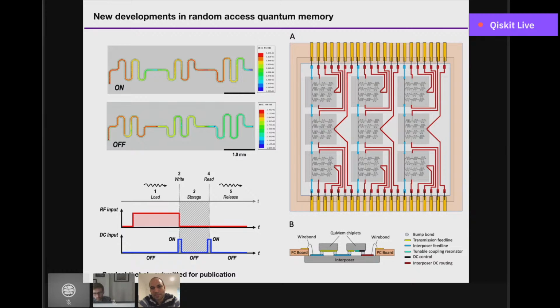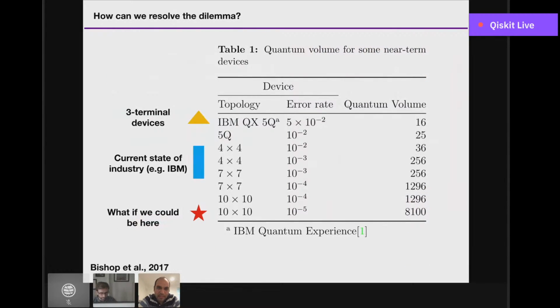So here we are arguing that you can actually scale this up into a quantum memory, somehow a classical random access quantum memory: the access is classical but the information is quantum, and you can maybe make up to 16 bit or maybe even 32 bit, depending on how you wire bond this. And there's a technology of how we can do flip chip and scale this up that can work with the hardware on the qubit side. So if the qubit is gateable, that's great. If the qubit cannot be gateable, you can still use this tunability at the hardware for other applications.